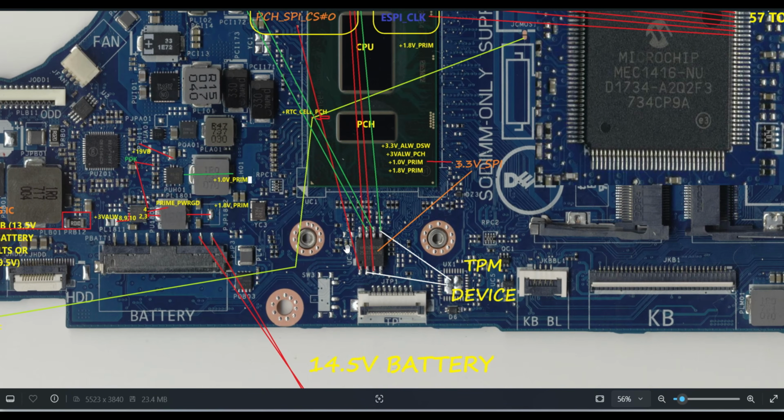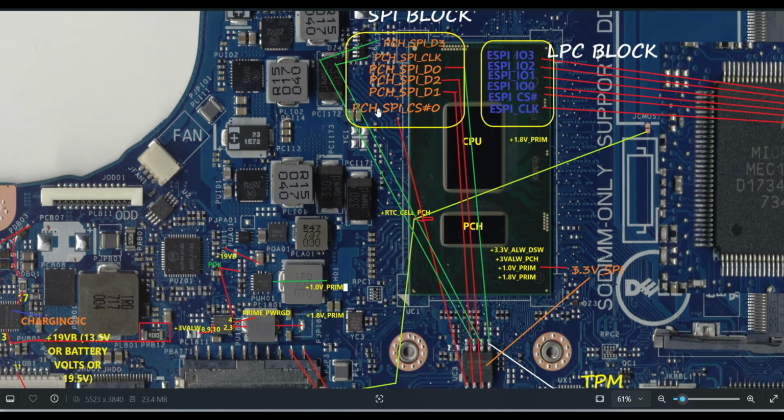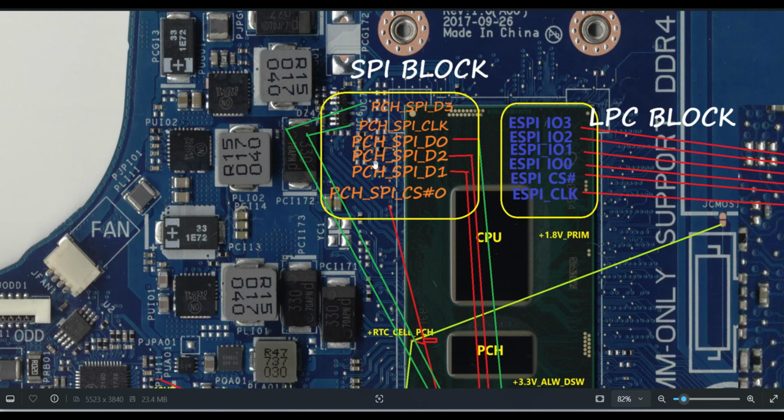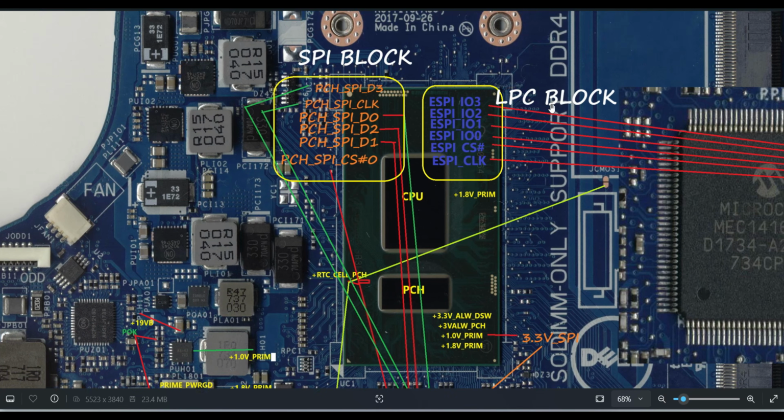So now see, this is UC3. From this UC3, these are the signals the PCH will receive. It will communicate through these signals. One is PCH underscore SPI underscore CS hash 0, then PCH underscore SPI underscore D0, 1, 2 and 3 and SPI underscore clock. These are the most important signals to communicate between the PCH and the BIOS chip.